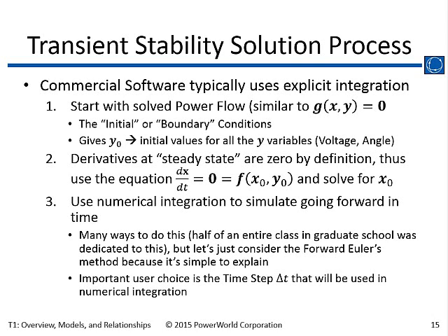But to do that, you need to have a negative sequence model and a zero sequence model for your system, and a lot of times those aren't in the data sets. But because we do fault analysis, PowerWorld can handle negative sequence and zero sequence models and then use them in transient stability. But we're not solving transient stability on the negative sequence or the zero sequence.